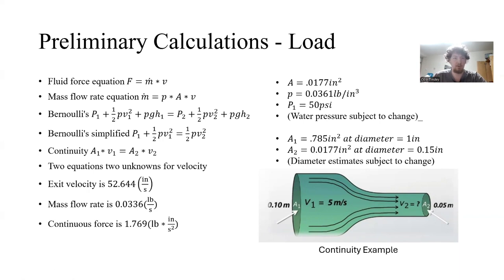Hi, I'm Cole Tinsley, and I'll be going over the preliminary calculations for the load that's against our deflector and will be causing the stress that we'll be analyzing. The fluid force formula is very simple. It's just the mass flow rate times the velocity of the fluid. And the mass flow rate equation is, again, very simple.